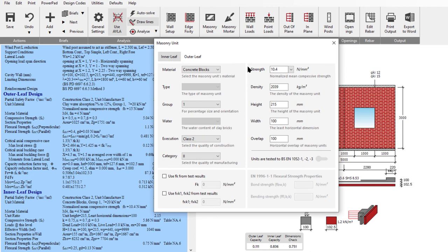I actually prefer the British approach, that it is different and should be taken differently, rather than just saying, oh well, we've lost half the area, so our axial is a half the capacity, and our flexural is 3/4 because it's on the outside that we got the material anyway. So yeah, it's doable in the program.